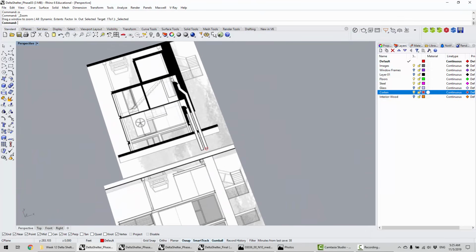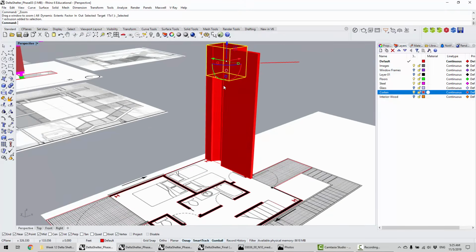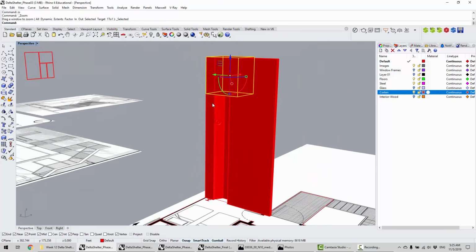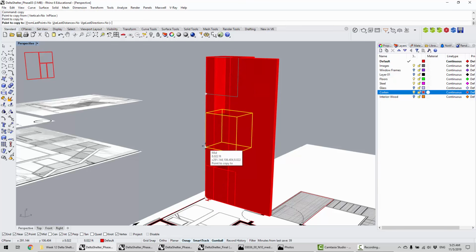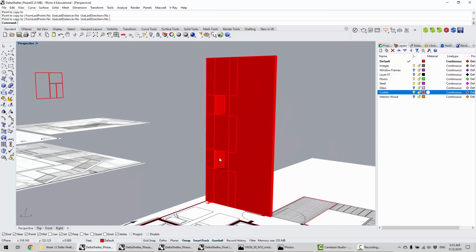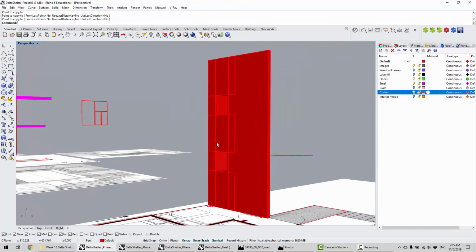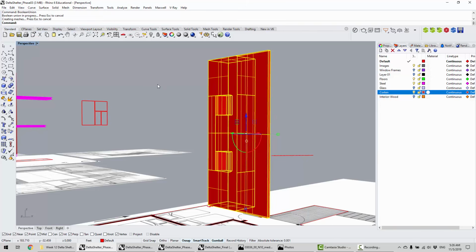So it's just that portion should be open, okay? So what you would want to do is do this, right? Make a box and do a Boolean union, right? You can obviously dimension it properly, but essentially something like that. So you just have the fireplace openings correct, and take all of these together, Boolean union, okay? And then merge all faces.